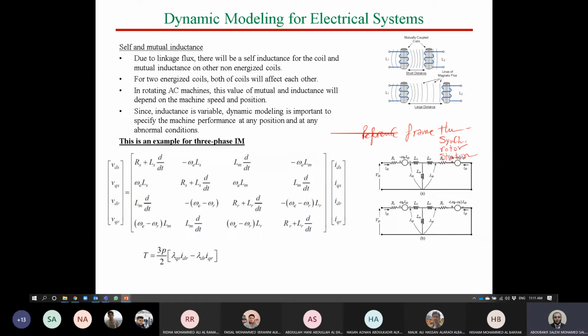If we have a voltage moving with a certain frequency, 50 or 60 hertz, if you are moving with this vector of voltage, you can see this vector as a DC supply. Is it right or not? Yes. So this is now the meaning of reference frame. So if we work with a reference frame now, we can simplify our models.